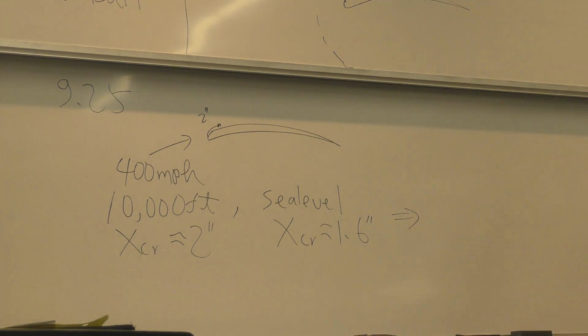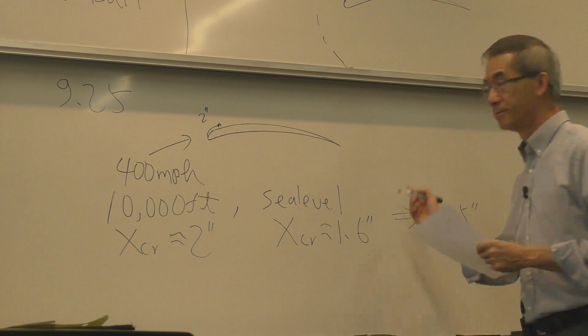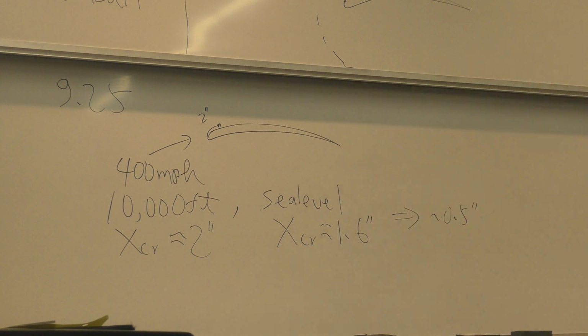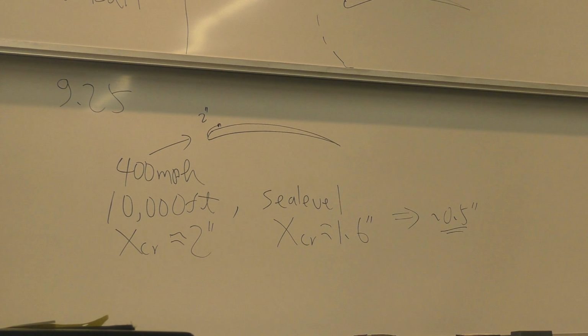due to the change in the viscosity and the density, and hence the Reynolds number, the location of transition is off by not much, half an inch. Do you think that will have any consequences on the performance of this airfoil? It turns out the answer is very much so. A seemingly so innocent half an inch difference on an airfoil can cause substantial performance changes on components.